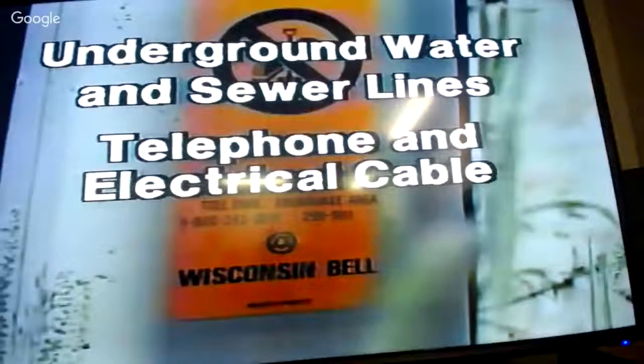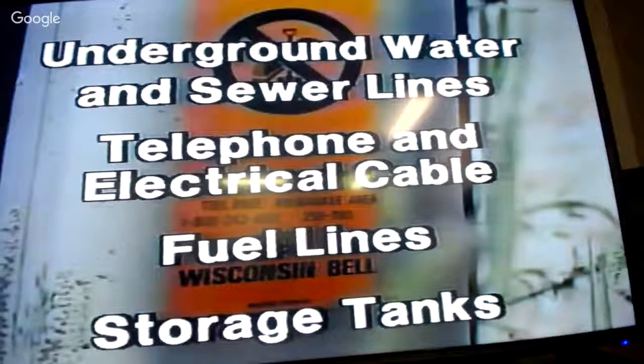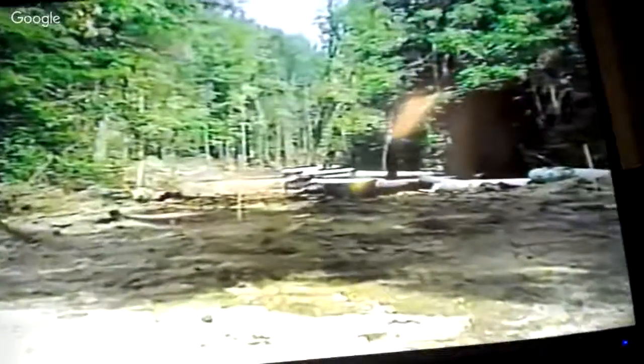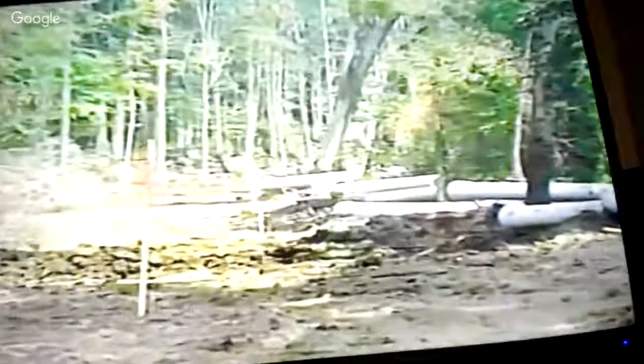and electrical cables, fuel lines, and storage tanks. Most areas have established a digger's hotline number. One phone call is usually all it takes to find out if any underground installations exist. If so, the proper steps for relocation must be followed.